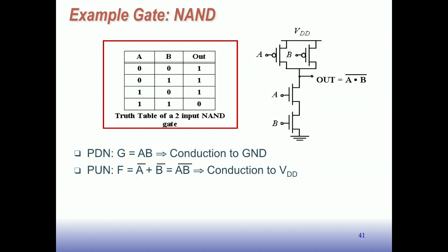We will see in our CMOS circuits, CMOS gates like this, we use P-type transistors for pull-ups and N-type transistors for pull-downs, and we don't mix those. And I'll talk later about why that is. But for now, you can make that observation.